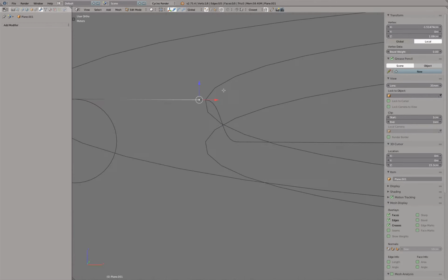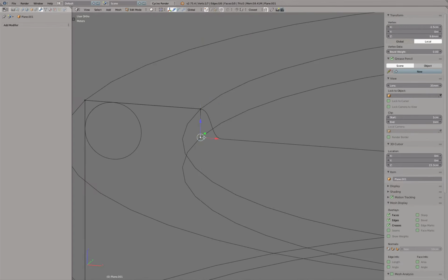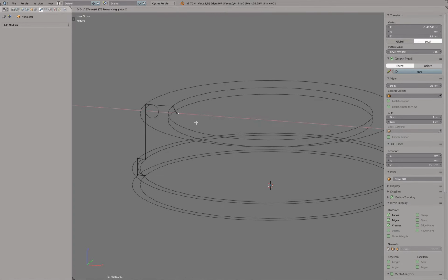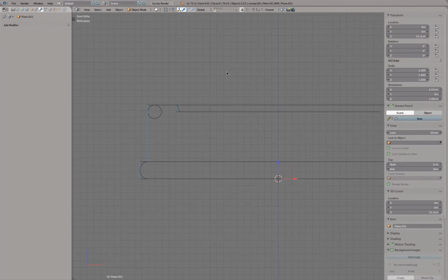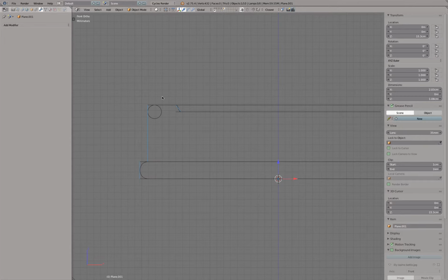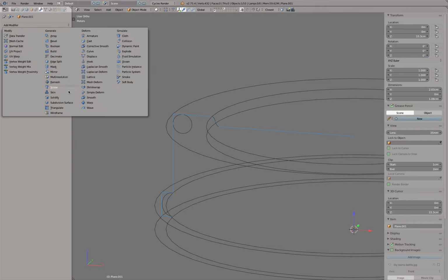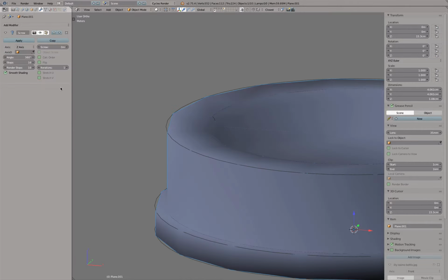Here we will sculpt this later a little bit, there, E and Z, snap to this point, but then I move it over to there, E and X, and then also here we type in 0. Now we actually have a very flat polygon model. This part I would like to be on layer 5, so I press M and 5. There, perfect. Now actually I can, for example, also here add the screw modifier.